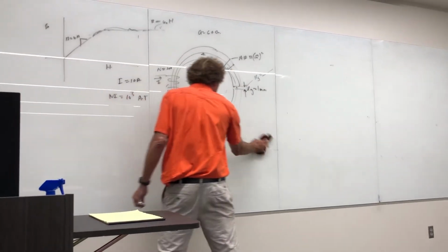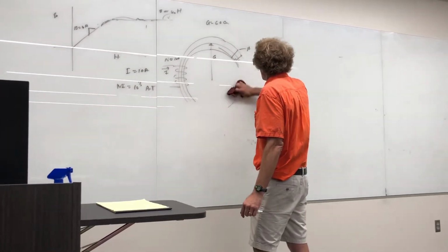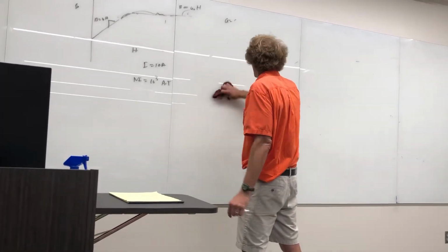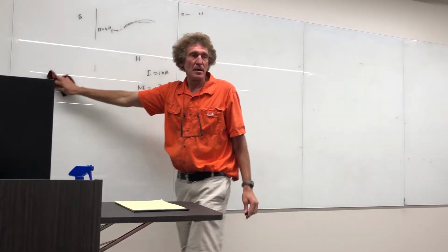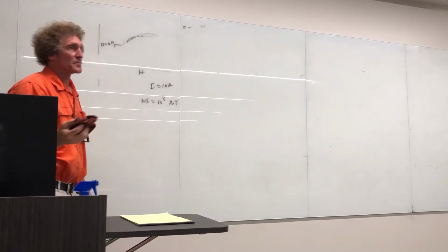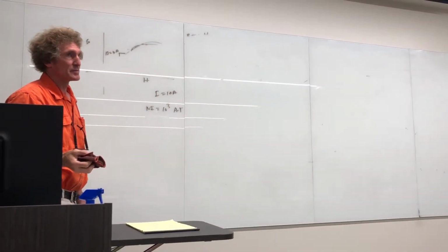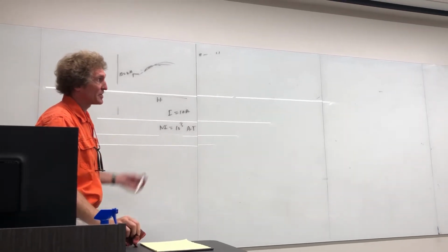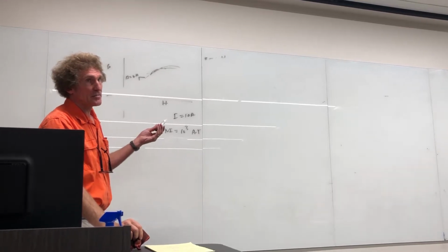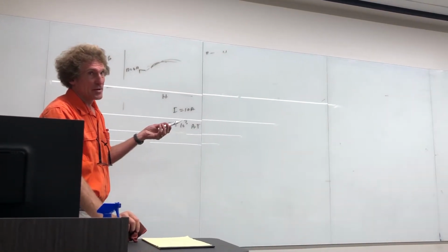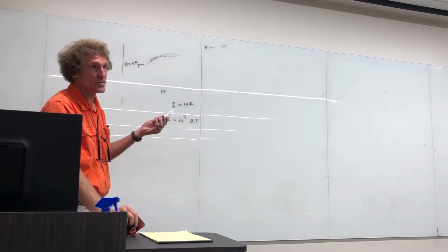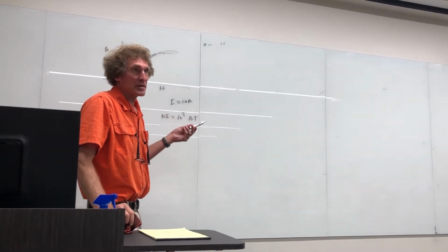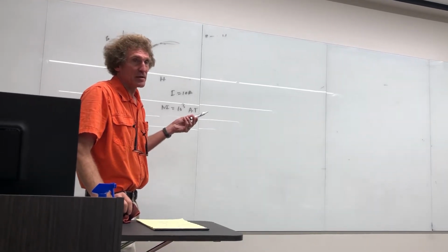Does he start by guessing that the core has no effect? Can you tell me? He guesses a B field and then uses that to find mu. He uses that to find the reluctance. Well, you can't just guess a B field. Well, that's what he does in the solution. Yeah, he assumed B equals 0.4. That means what he probably did is take Ni divided by the reluctance of the gap, right? If you take Ni, that's 1,000. What's the reluctance of the gap again? 2.53 times 10 to the 6th.